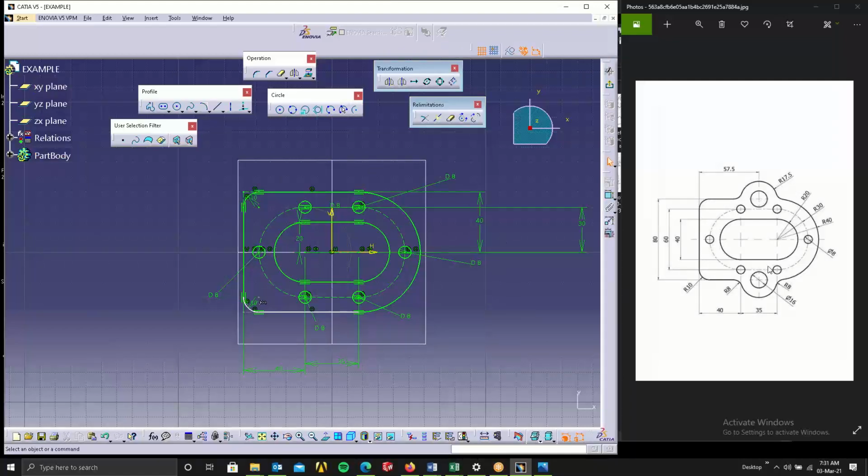And here we can see there are two more circles at this location. Then we click on circles at this point. Select one circle. Make sure it's not tangent to anything. Similarly, here also just select one more circle. Make sure it's not tangent or connected to anything else. If it's connected, then again you have to delete that connection. So it's an unnecessary waste of time. Here, when you're doing it, you can offset it. But since we are not using those tools, just stick to the tools you are using.